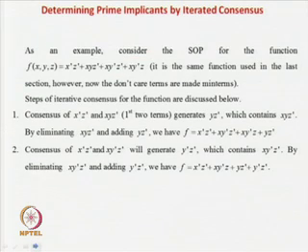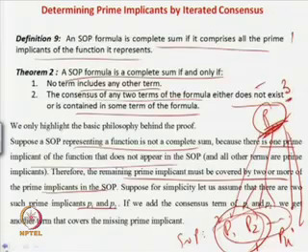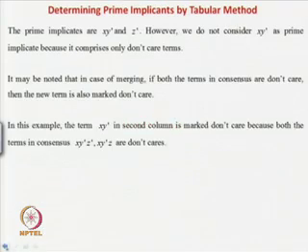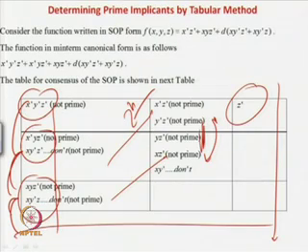Okay. So now we will take an example. Always this type of complicated definitions are better illustrated by example. So we take this function. If you remember in the last class, this was the function: x prime z prime, x y z prime, and this one. This is the same function as in the last lecture. However, the don't care terms are here min terms. If you remember, this was our example in the last class. So this was our expression. In this case, the last two terms were don't care terms. Now we have eliminated the don't care and we make all those min terms.